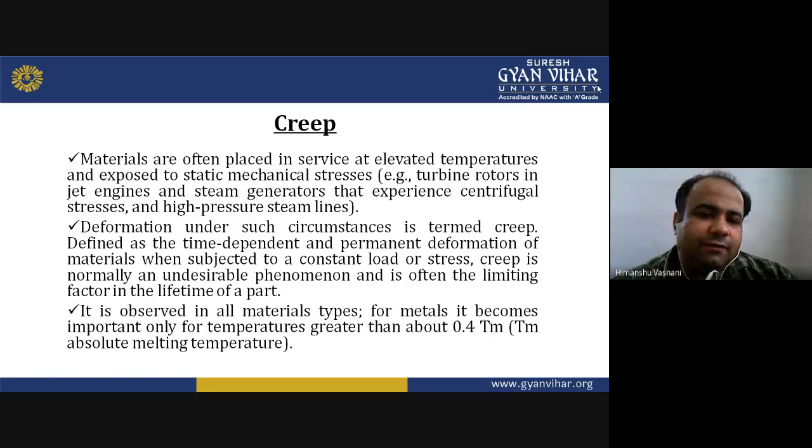Applications like turbine rotors in jet engines are prone to such deformations. Creep is normally an unfavorable, undesirable phenomenon and is often the limiting factor in the lifetime of a part. Obviously, if it leads to permanent deformation, it is undesirable.